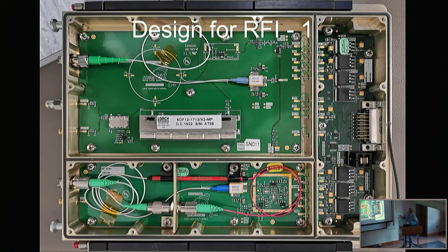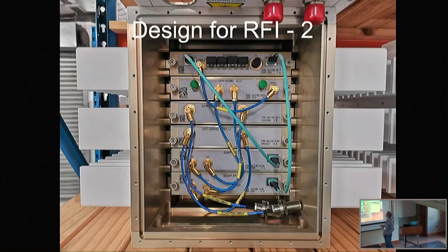You put those printed circuit boards into enclosures like this, and here you can see the RFI gasket. So this is one module. This is actually a timing module that goes inside the digitizer, and this RFI gasket shields this section from this section, two different sections, from the power supply section with a filtered connection that goes out. And you said these are different ground planes in the board? So you try to shield everything between ground planes, sandwiched between ground planes, so multi-layer boards, yeah.